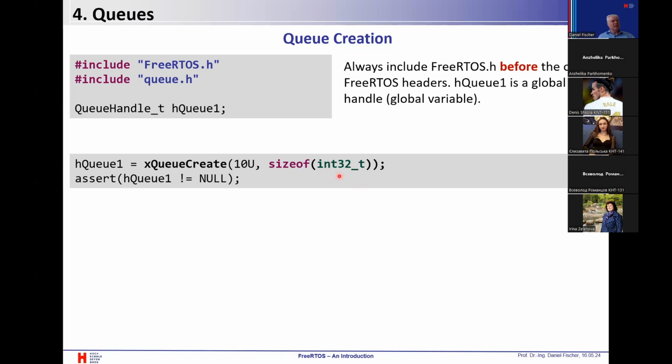Here you can see this is a signed int variable with 32 bits, because the size of an int itself depends on the specific platform. By using these typedefs, you see directly how many bits or bytes the used data type has. So never use int, char, or anything like that in your embedded code. Use these typedef data types.